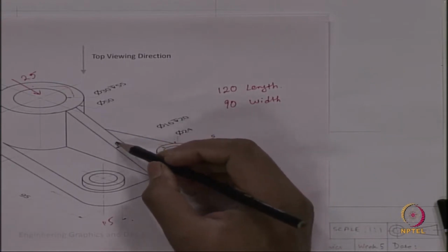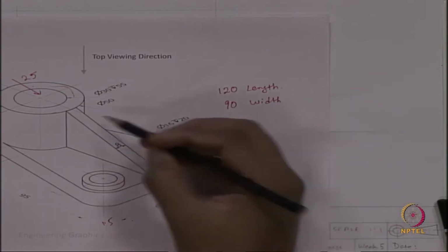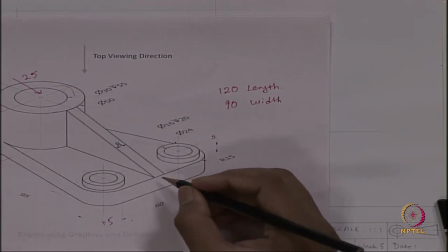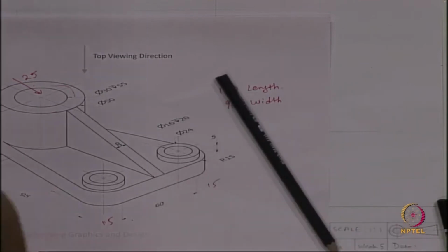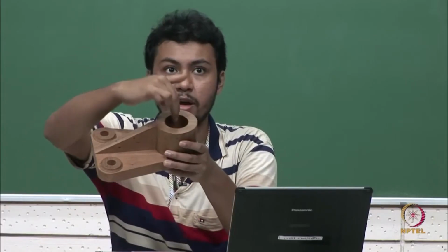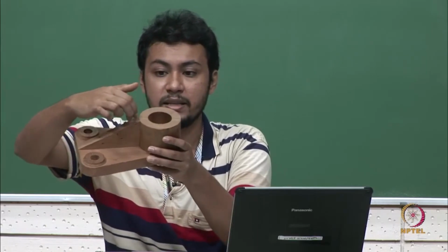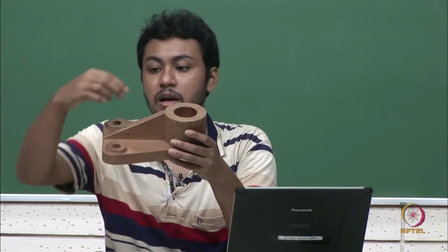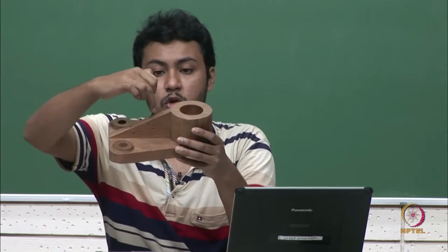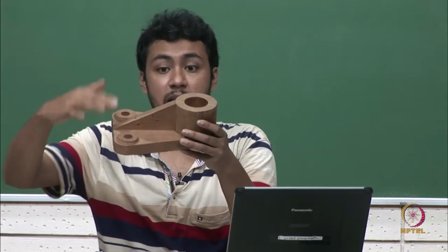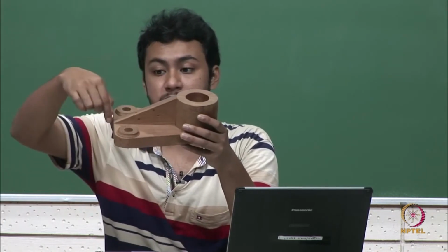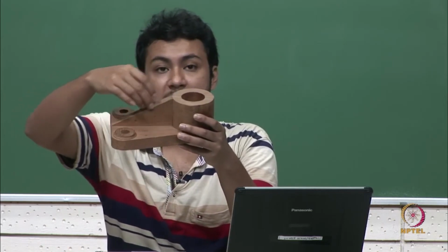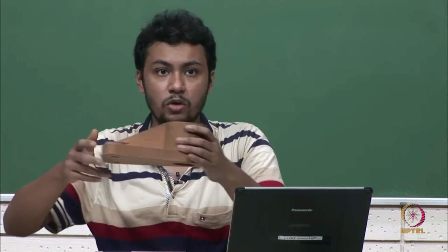this rib. We will draw this rib, and this rib has been started from the end of the circle and ended here. If we look at the rib in this zone, you are looking first at this circular part, then the rib is coming. The rib has been started from here and ended here. If you look at it from the top, you won't see an inclined surface, rather you will see just two lines, a simple rectangle instead of a slanted rectangle. So, that we will draw.